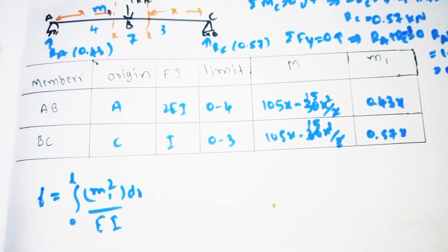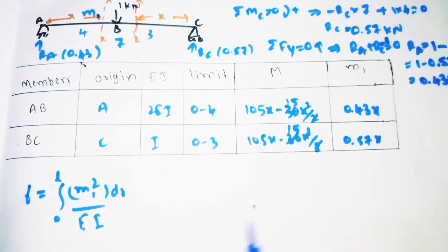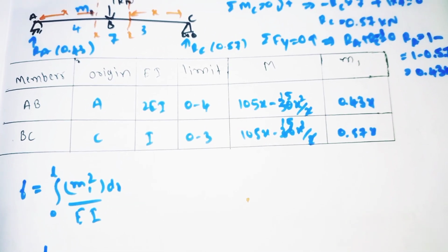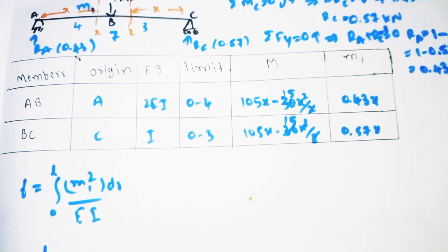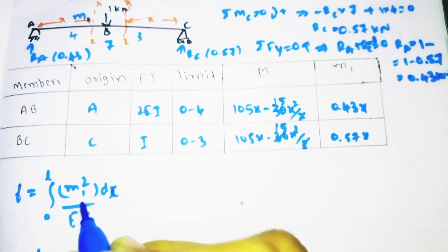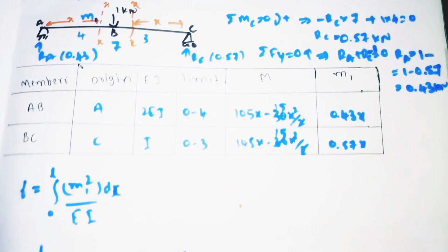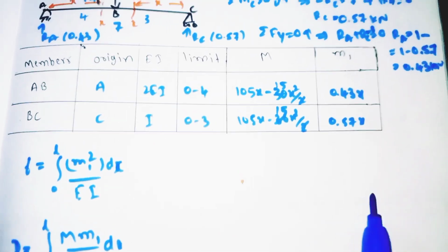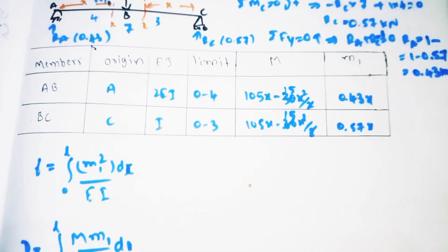Similarly our displacement also comes only one, D equals integration of 0 to L capital M into small m1 divided by EI into dx. If we had M2, then we would need to find f11, f12, f22, f21 like that. Here we have only one moment, so now we need to find F and D.